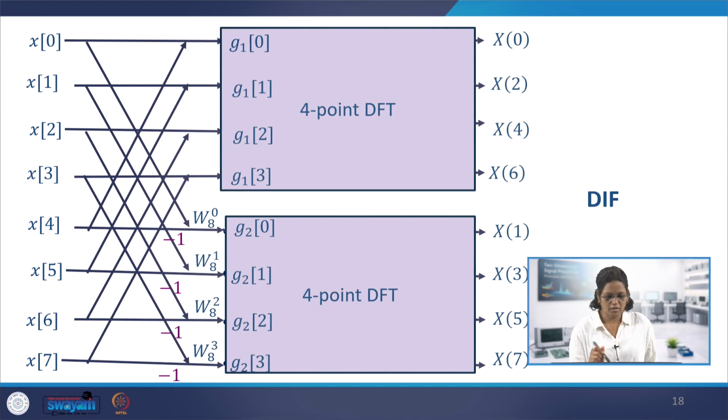So taking the DFT of this, x of 0, you can see we have not given the bit reversed order. In DIT, you have to give it in the bit reversed order, that is even and odd. So this is given as such in the order. The decimation is done here: 0, 2, 4, 6 and 1, 3, 5, 7 like that. So you get G10, and in the previous slide we had explanations about this equation. You can see the twiddle factors coming in and then pass it to the 4-point DFT, get the DFT here.